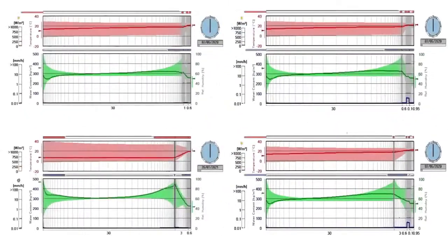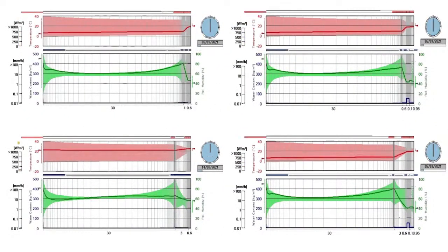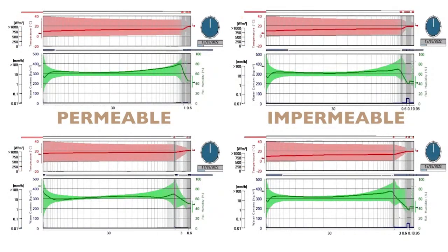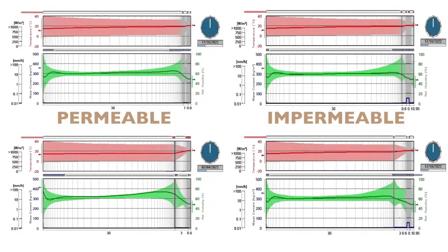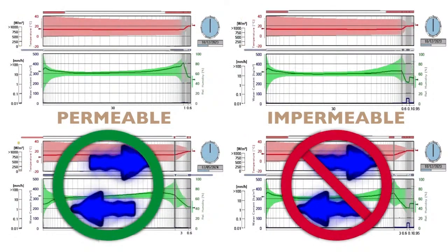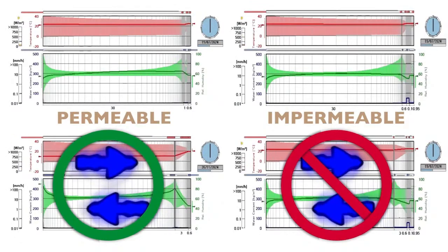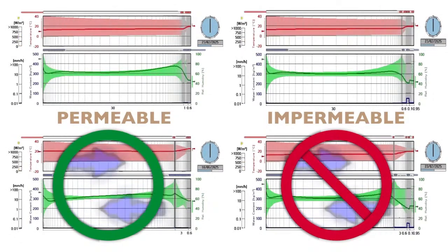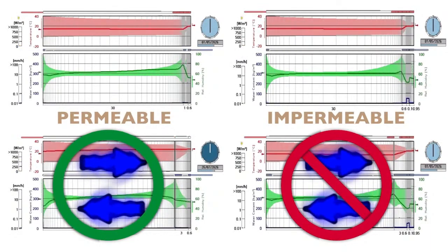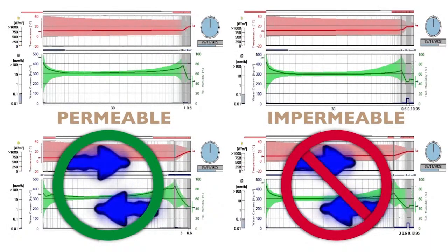As can be clearly seen, the permeability of the Spacetherm multiboards allows for a greater drying out of the construction, as this is possible to both the interior and the exterior of the building. This results in much greater swings in the value of the relative humidity, but the values are lower overall than when the vapour checking Spacetherm wallboard is used. If we then look at the water content of the stonework, this can also be seen to be lower when thinner and more permeable insulation is used.